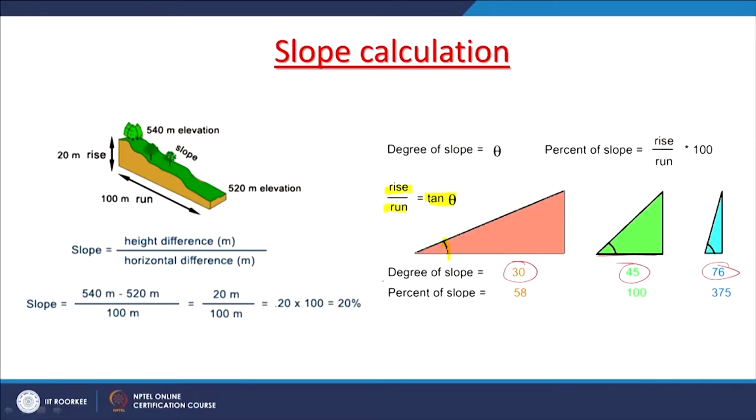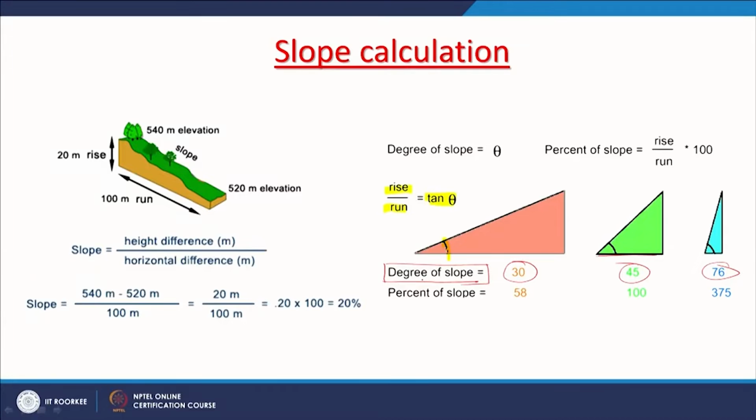By default, in most GIS software, you would find that they will derive your slope in terms of degree, because our brain is much better trained to understand degrees rather than percentage, but the option is definitely available in most GIS. It is a simple calculation: instead of having 0 to 90, you can have percentage from 0 to 100.